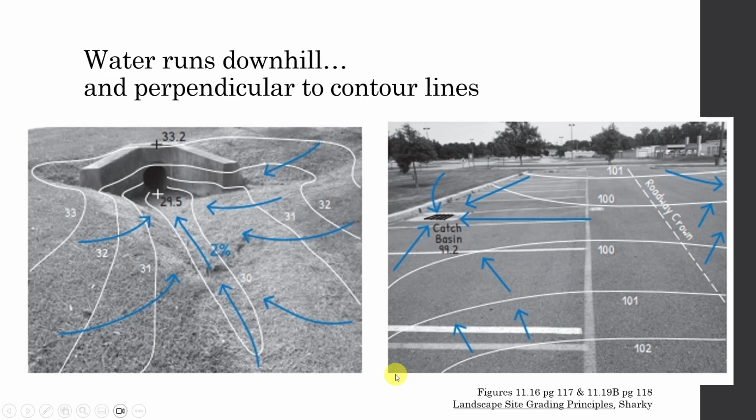On the left-hand side, we see a swale solution. And you can see that the low point is right here, and then there's kind of a valley effect. And so the water is going to come always perpendicular to these contour lines, perpendicular, perpendicular, until it hits this lowest section here, in which it will run perpendicular to this contour line and down to the lowest spot elevation.